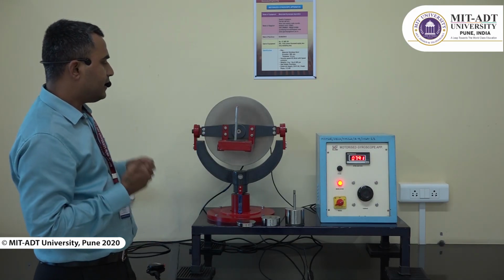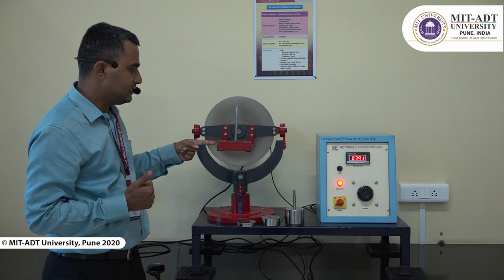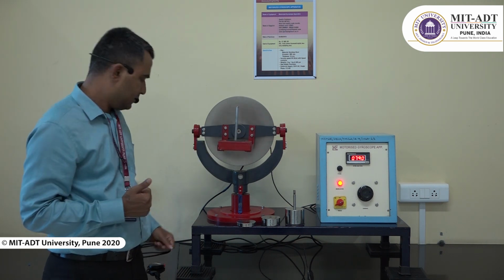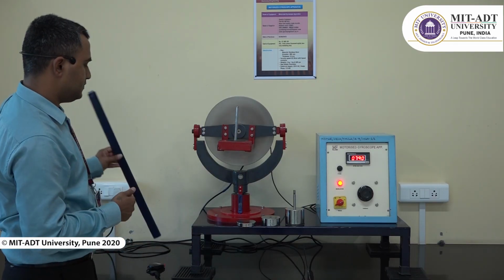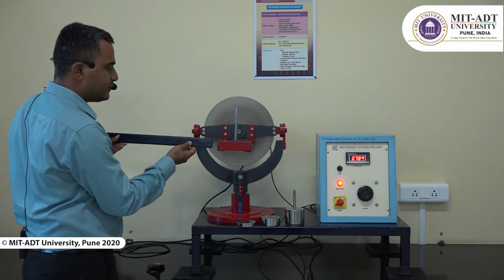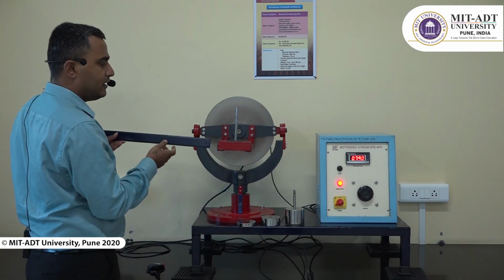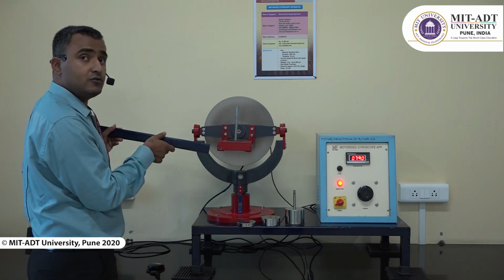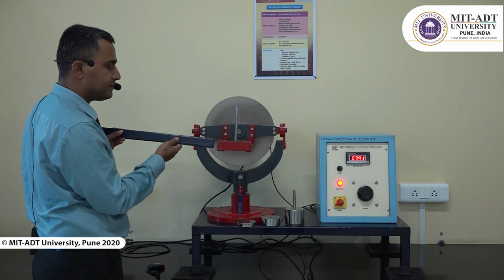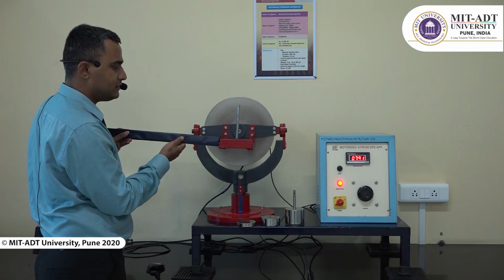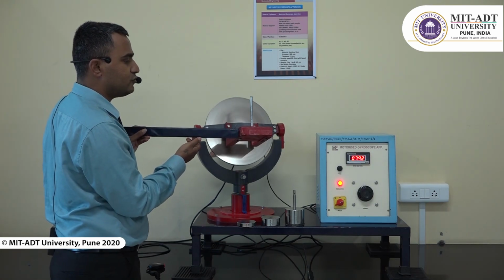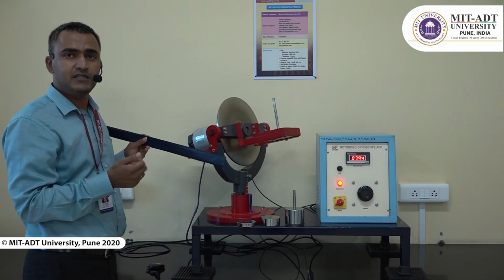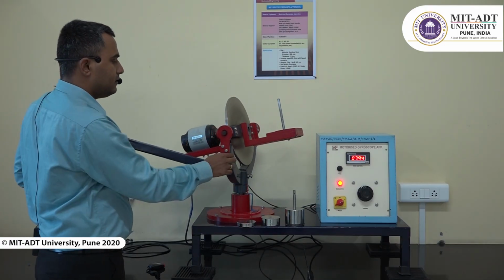Now I will just try to push this axis of spin on that side. Let us push gently the axis of spin towards this side, and we will observe where exactly the reactive gyroscopic couple is going to play. Okay, so gently push this. See, the reactive gyroscopic couple is taking axis of spin in upward direction. That means what? When I have